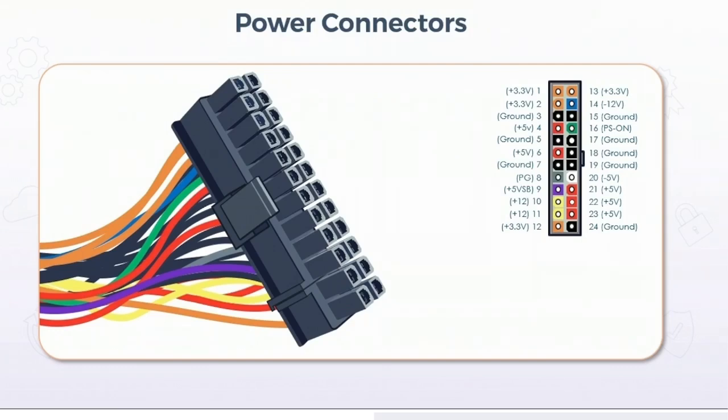So if that was the case, you simply separated the smaller connector from the larger and installed that one separately into its own dedicated connector, usually located fairly close to the CPU itself. If, however, the main power connector had 24 sockets, you simply left both pieces attached to each other and inserted all of it into that single main socket.